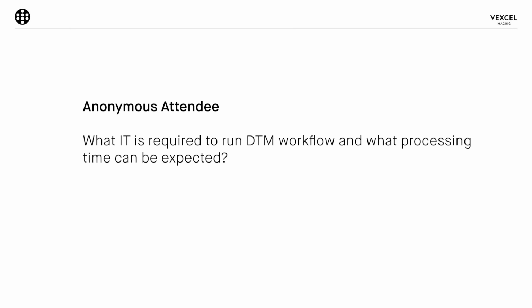Depending on the number of CPUs, we recommend a minimum amount of memory. The lowest we recommend is 4 GB RAM per CPU core for the processing.